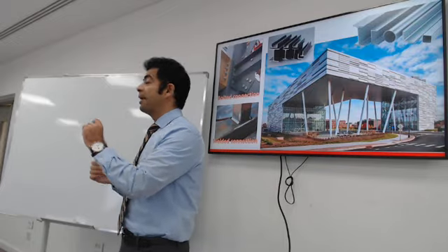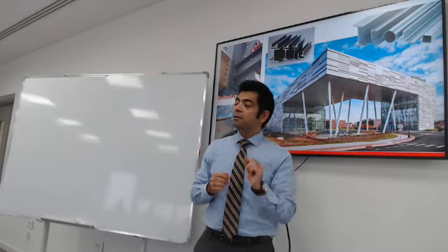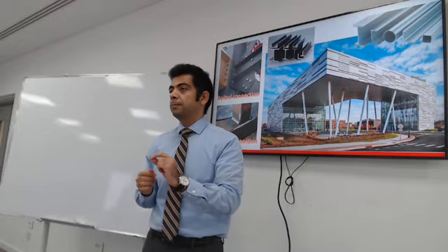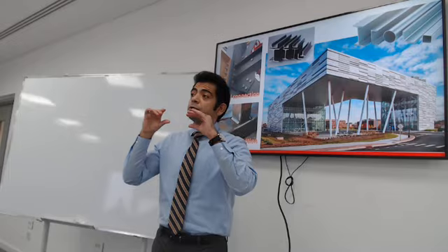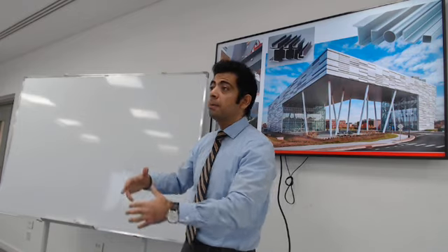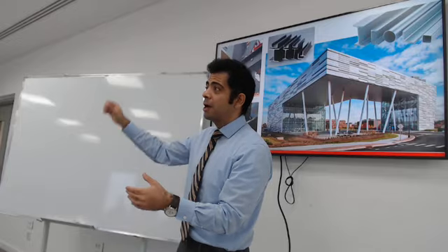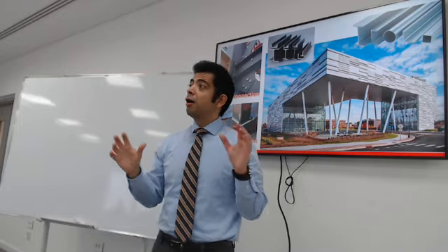The idea I wanted to share with you has to do with how steel structures are fabricated. Usually before you do construction, the structure is made into pieces in a fabrication shop, and then it's shipped to site, and then it's assembled on site. Unlike concrete, where you can mix the concrete on site and pour it in the formworks. It's a very different way of erecting or building up steel structures.